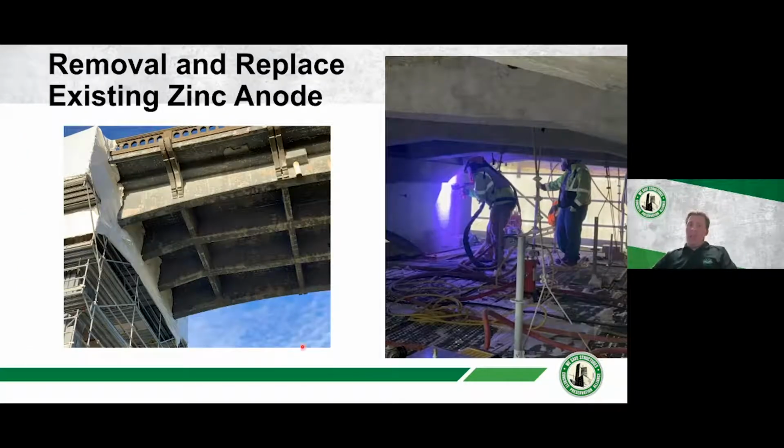So at Yaquina Bay, since it already had a system, we had to remove the old zinc system. As you can see in this section of slab, it's rough looking. There's a lot of it that's flaked and delaminated and fallen away. There were other areas of this bridge that looked great. The zinc was well adhered and sound onto the concrete.